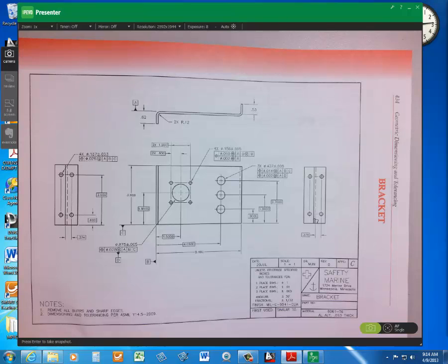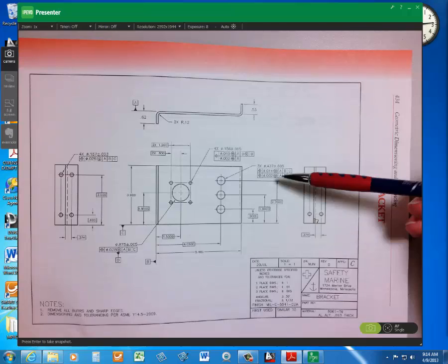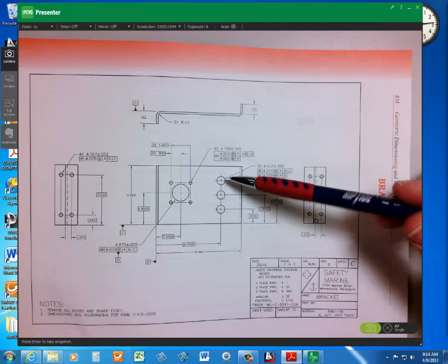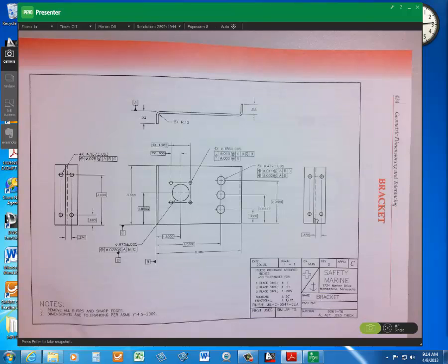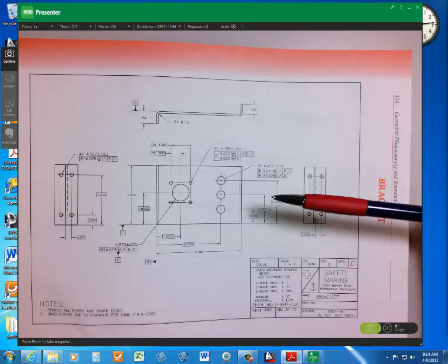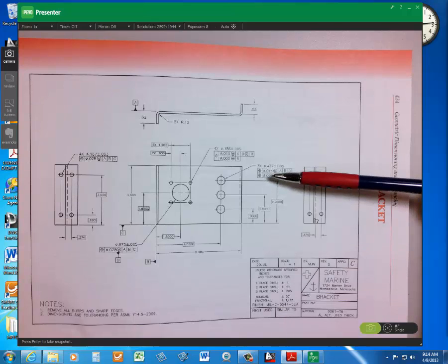All right, next, 437. So we got 3 holes. And this one is a kind of funny word, a two single segment feature control frame. The upper part of the feature control frame specifies your pattern of 14 thousandths MMC, where the pattern of features lie in a group relative to A, B, and C. No modifier.